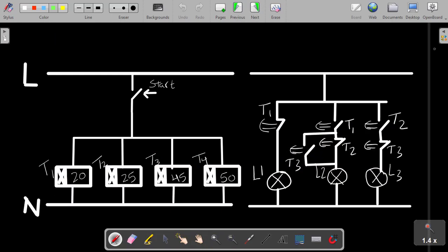As you can see here, we have 4 timers. Those timers are on delay timers. And we illustrated before in the classic control course what on delay timers are. On delay means that all the auxiliary contacts of this timer, let's say T1 is here, one normally closed and the other contact normally open, will stay normally closed and normally open until this timer counts down to 0.